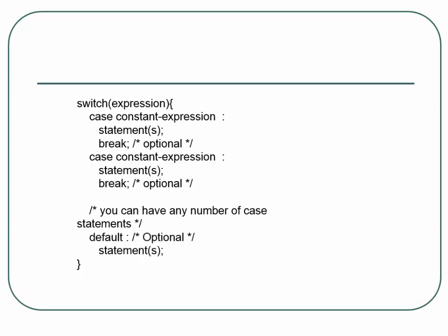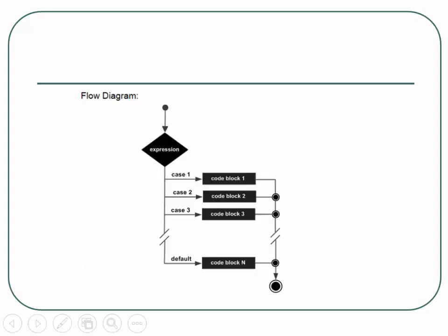And I do two of these. We won't get into the details too much of that. But you would have a case for every possible state in your state machine. So if you have 20, you could do this with serious if-then-else statements. This is the reason why I backed off of trying to do this in assembly. If you try to do this in assembly, you have to use the jump commands, and it gets relatively ugly very quickly. Finite state machines are much more suited to using C. You can use other languages, but use the right one.